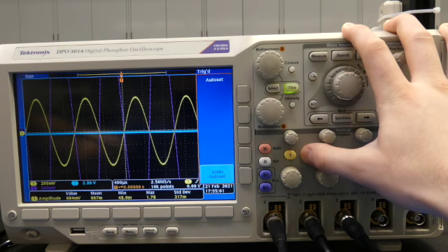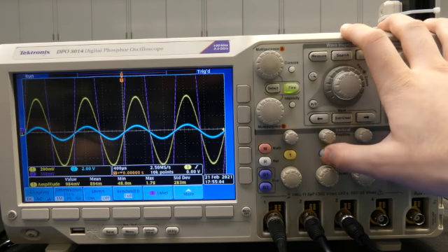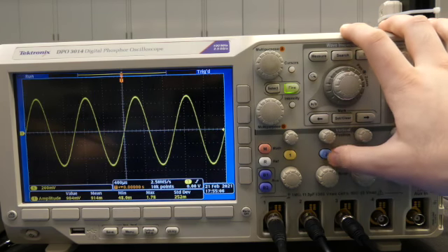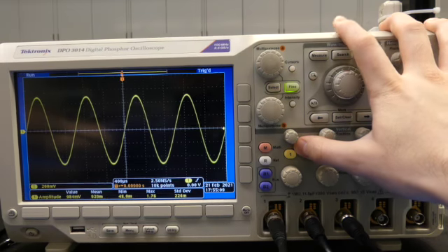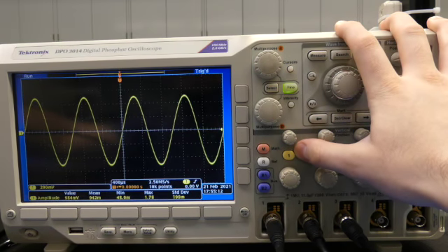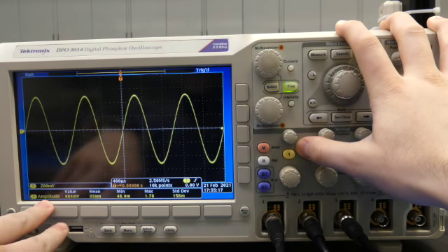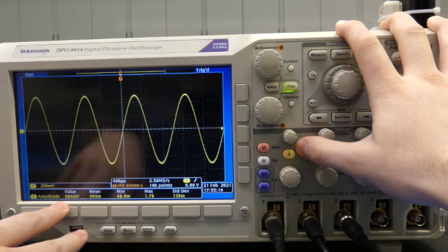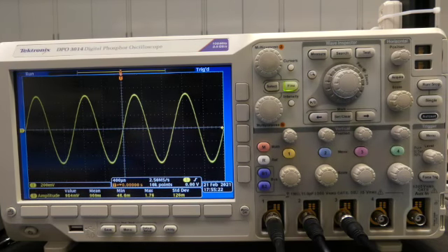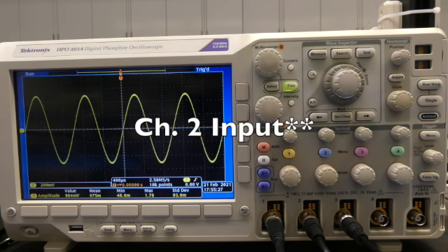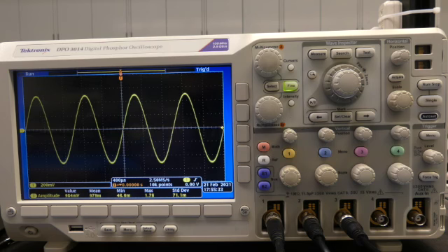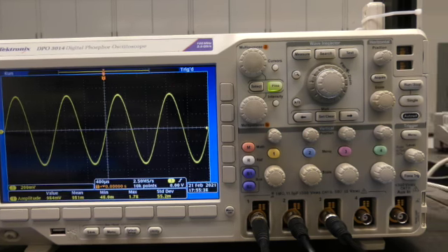Okay, I'm going to turn off the other channels here. Channel 1. This happens to be my channel 1 output. Okay, you'll see that I have the amplitude set up already, which I'll show you how to set up amplitude measurement. But it says about 984 millivolts, which you'll have to trust me on this because I don't want to move the camera over right now. But my channel 1 output is set to 1 volt, so that makes sense, or 1 volt peak to peak. So that's roughly equivalent to that value in amplitude. Okay, so that's my channel 1 input.